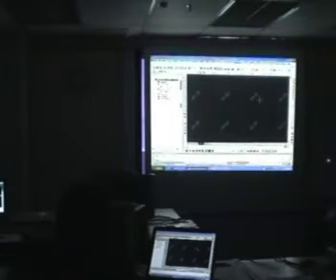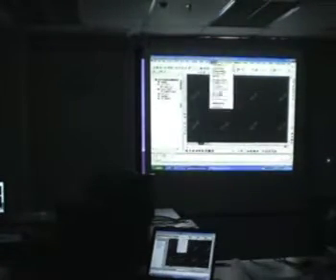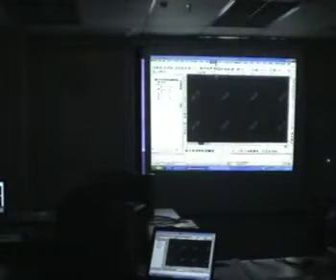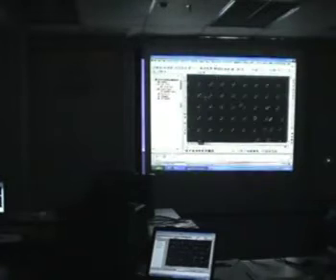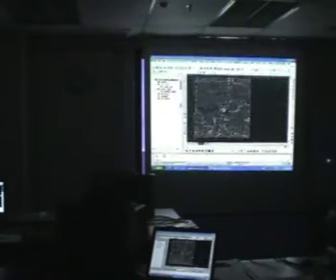So with Land Desktop, you can convert these 2D text into 3D points. I have to admit, it's not a very direct conversion, but it is possible. A lot of users of Land Desktop think it cannot be done because they can't find any function that says convert 2D to 3D. Just because it's not there doesn't mean it can't be done. It can be, and I'll show you the steps. We can't do the conversion directly from this drawing.